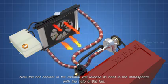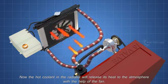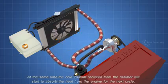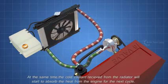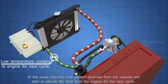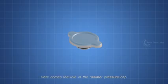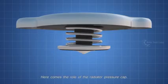Now, the hot coolant in the radiator will release its heat to the atmosphere with the help of the fan. At the same time, the cold coolant received from the radiator will start to absorb the heat from the engine for the next cycle. Heating liquid inside a closed system always builds up pressure. So, how to maintain the pressure? Here comes the role of the radiator pressure cap.